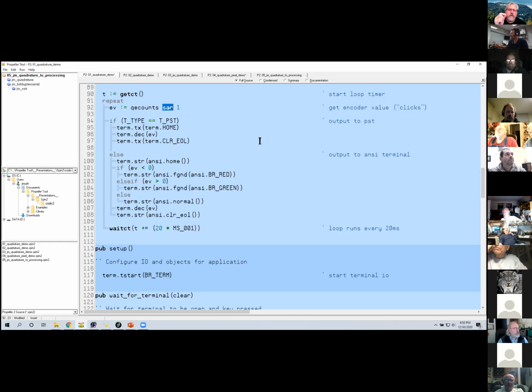But if your multiplication or division is a power of 2 number, like 2, 4, 8, 16, 32, etc., if it's a power of 2, you can do it with a shift, which is a very fast way to do it. Now, when you do a left shift, which is for multiplying, the LSB end gets padded with zeros. If you do a right shift, the same thing happens. Here's the problem. If your value was negative and you do a right shift and you put a 0 over on the MSB end, you've just screwed up the sign.